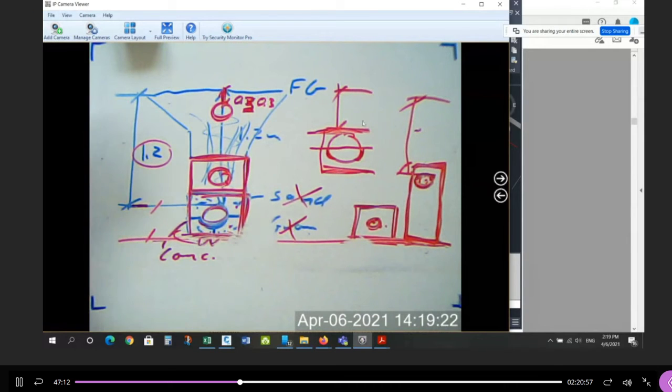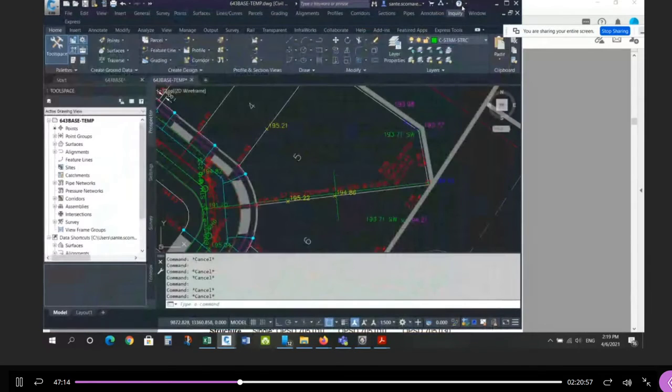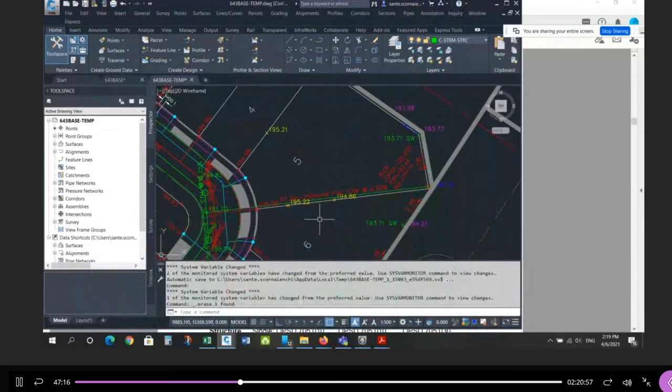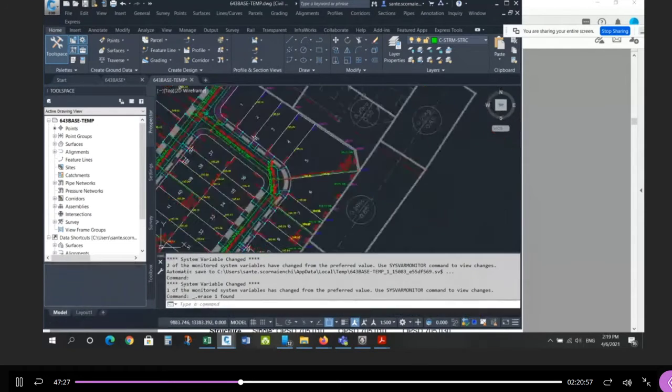So in combination, the two techniques, again, are flatten the pipe as much as you can. So I use the 0.25% instead of the standard 0.5%. And then the ones that are still misbehaving, I raise them. And that's the calculation you need to perform.